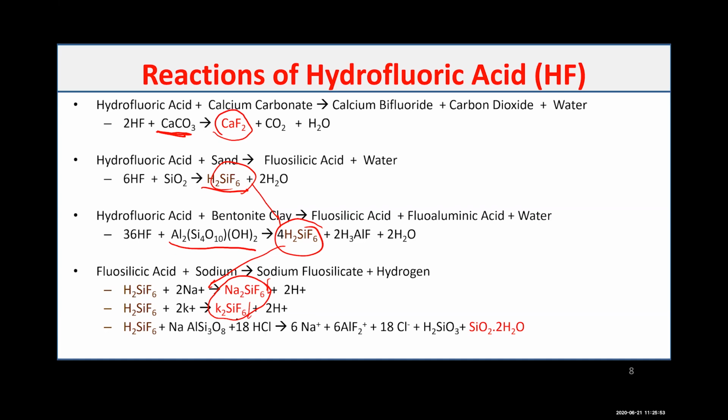And there is a pretty way to overcome this precipitation by design. First, we combine HCl with HF. One of the reasons we combine HCl with HF is because of this material. This material does not precipitate immediately at pH of 0.